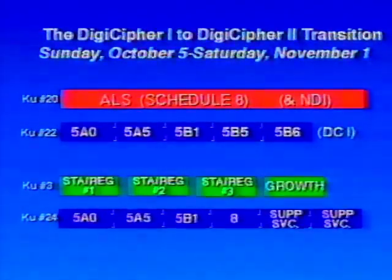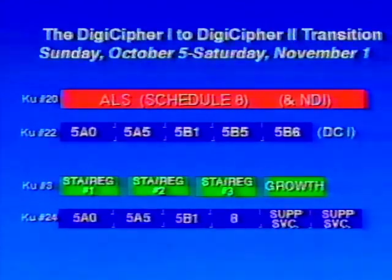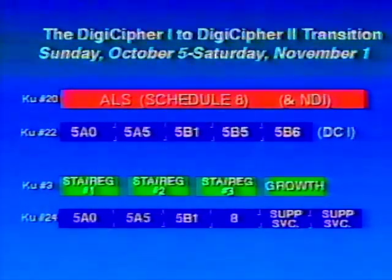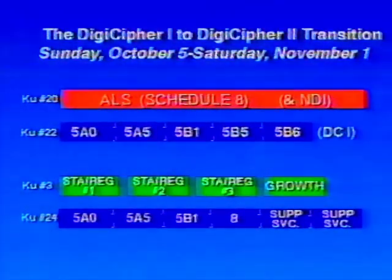We've just told you what we'd have on transponders 20 and 22. That's the ALS analog and the Digicipher 1 feed. But now we're showing you on this slide Ku-band transponder number 3, where we'll have 3 channels of station and regional network SCPC, that's Digicipher II SCPC feeds, no longer backhauling on SBS 5, but now available to you directly. And on Ku-band transponder 24, a 6-channel MCPC. Let me touch on this one briefly.